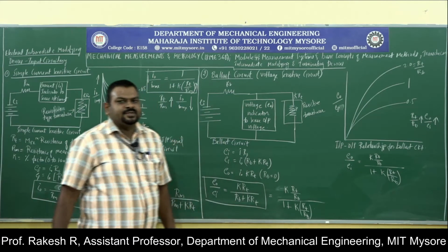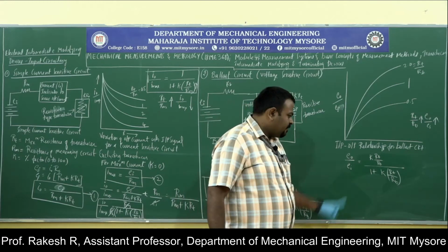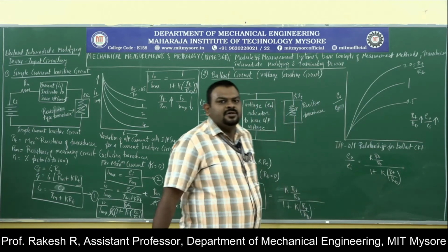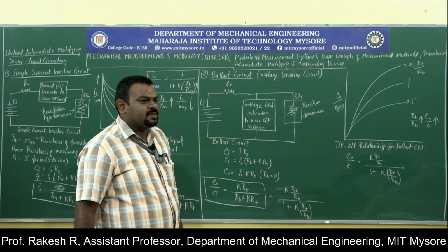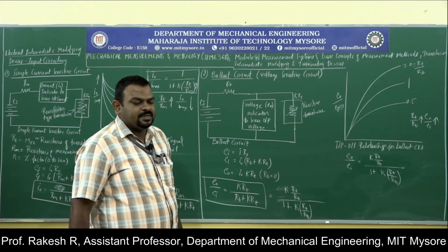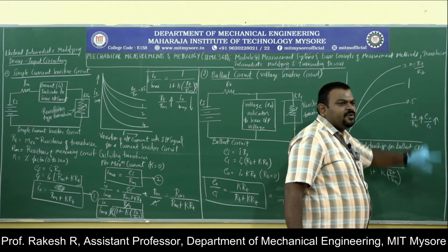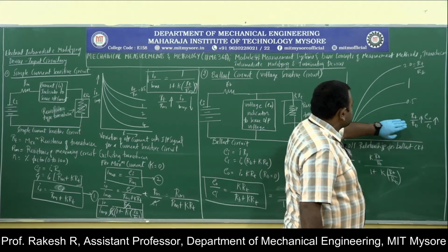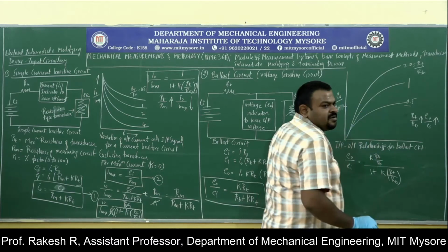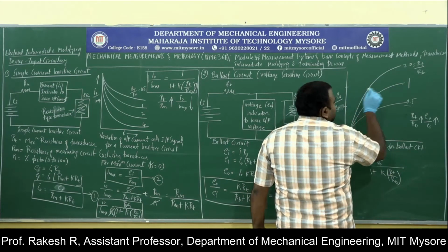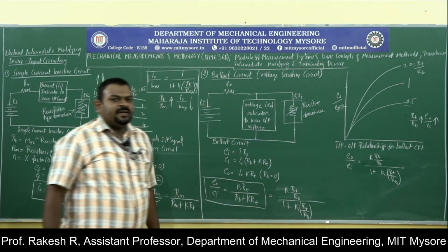So how far can you increase it? If you increase beyond some value, the denominator will also increase. This means the impedance of the circuit may be affected because of larger variations of resistance. Here, larger variation of RT by RB leads to sensitivity to the change in voltages. So this is the value we have seen. For 0.5, E0 by EI is less. For 1, E0 by EI is slightly more. For 2, it is more. As you change the resistances, the voltage is also changed.